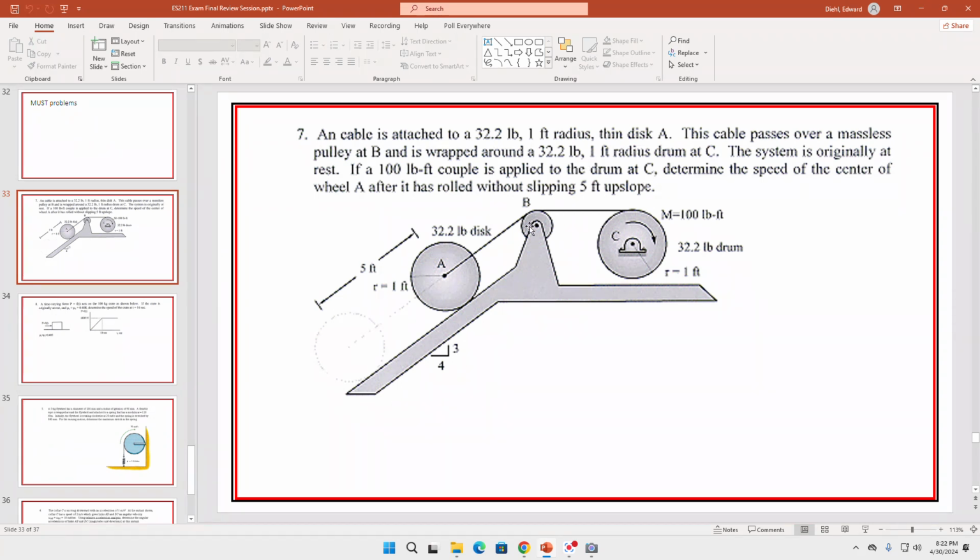We don't want the hassle of it, so you couldn't use Newton's second law with just the assembly because there's 2 points of support right here and right here. And you want to eliminate the points of support, but you can only do it one time with the summation of moments. All right, so that's kind of the reason why. So in this situation, we couldn't do it. In the other situation, I think we can.